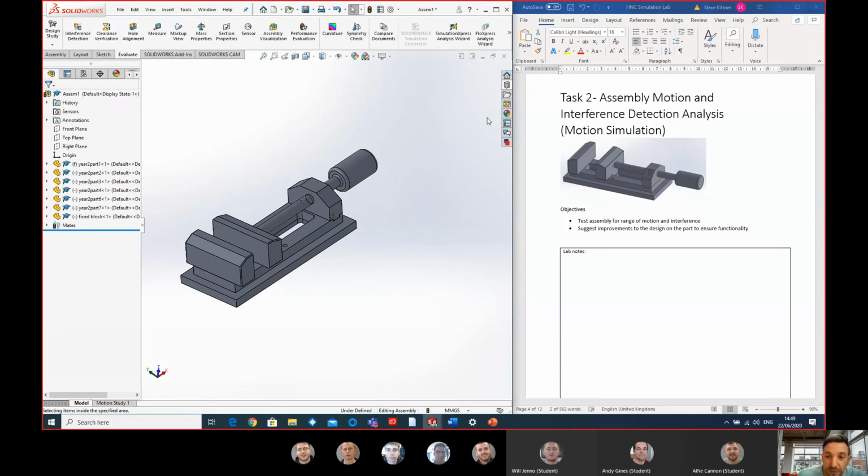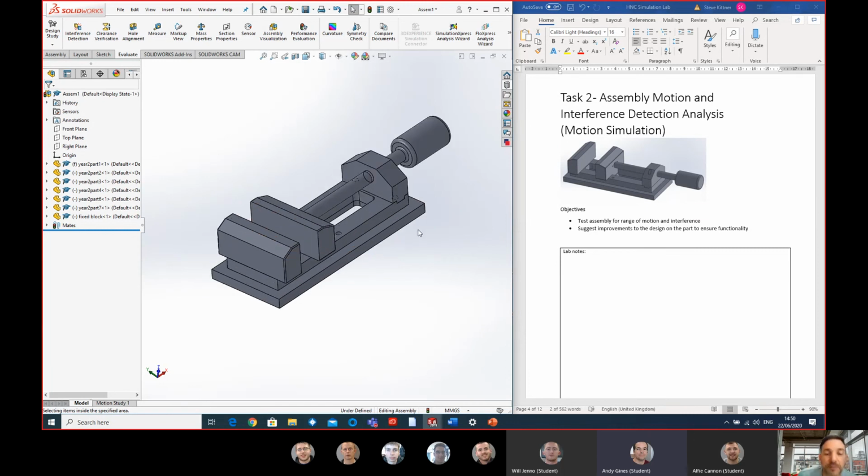You start getting into problems when you get people uploading models as surfaces, and not solid objects. We've had that problem before because we've tried to put clamps and linear bearings in and they've not worked in simulation, and it's because they've been a surface, not a solid object on their own. But that was in CATIA rather than SolidWorks, and the simulation in CATIA is not very good. No, and to be honest with you, the data that you'd get in SolidWorks probably isn't great either.